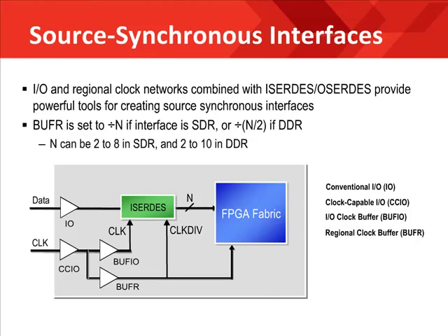Please note that all of this, that is, the clock buffer, the networks, the regional driver, the ISERDES, are all in one clock region in one column. This is how extremely high speeds can be achieved with the I/O resources in Virtex-6.